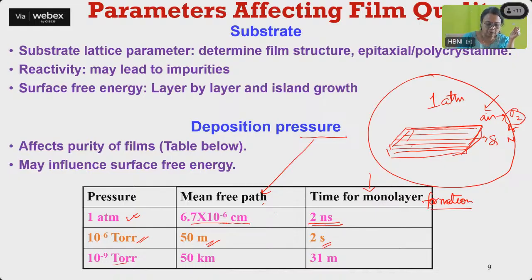And if it is 10⁻⁹ torr, which is an ultra high vacuum, which you can get using a sputter ion pump and all those things, the mean free path increases to 50 kilometer, and the time for monolayer formation is 31 minutes. So if you want to get a very good single crystalline or even polycrystalline, but good quality and high purity thin film, you should have a pressure of this kind inside your chamber.